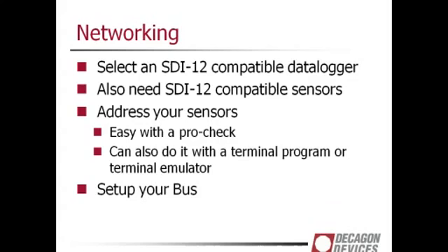So when you're actually networking, first you need to select an SDI-12 compatible logger. Your logger manufacturers, there are several out there now, they can help you out there. You'll also need SDI-12 compatible sensors, and then you need to address your sensors.